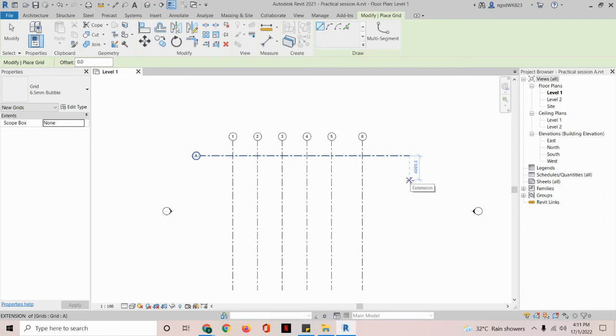So in Revit, it is actually very smart. If you look at my screen here, they actually give dotted lines. These dotted lines are showing you that the point that you're going to click is going to be aligned to the previous grid line that you made. And then you can move it up and down. It will show you the dimension, meaning how far away you want it to be. So let's say, for example, up to you. Don't have to be accurate. Follow me 100%. You just click on it, and then here you click one and two, and you'll get your grid line for another one.